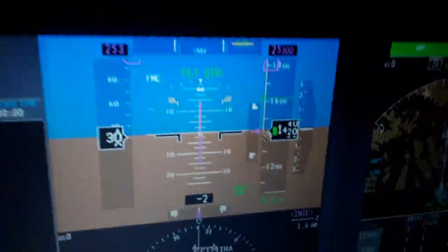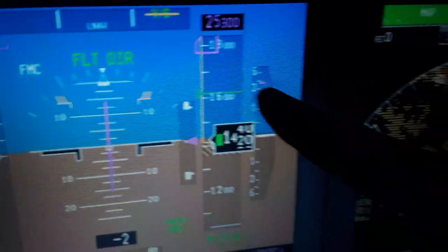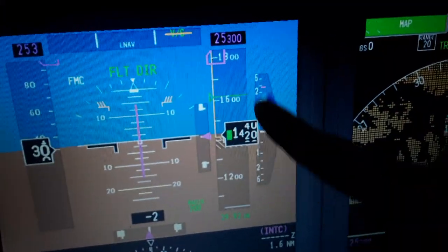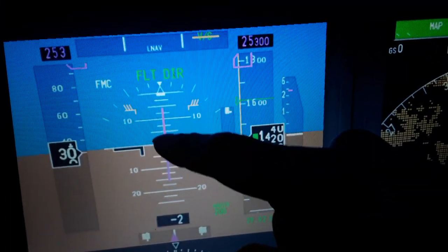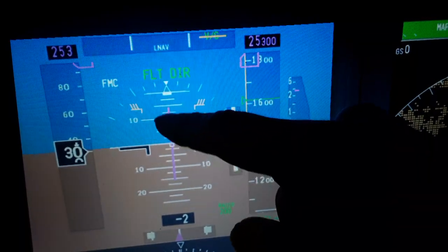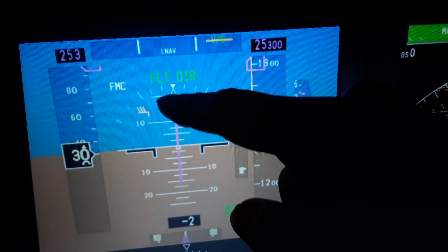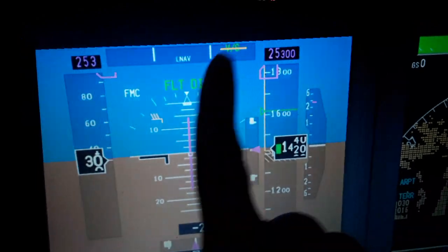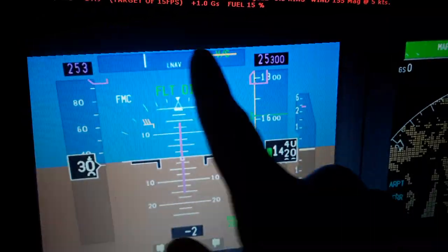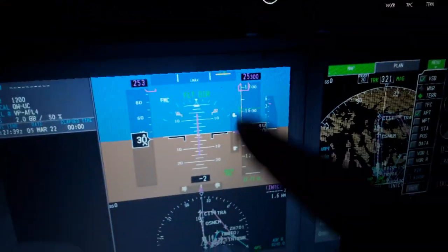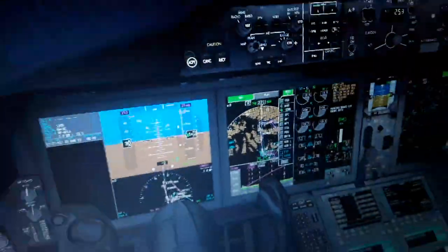253 knots. So you see the airspeed indicated over here. The barometric altitude, as I told you, the vertical rate of climb descent of the aircraft 10,000 feet per minute, the vertical speed indicator, the pitch attitude 2.5, 5, 7.5, 10 degrees, 12.5, 15, 17.5, 20, pitch up or pitch down, the bank angle as we fly, flight mode on 0, angle of attack, radio altitude above ground level.